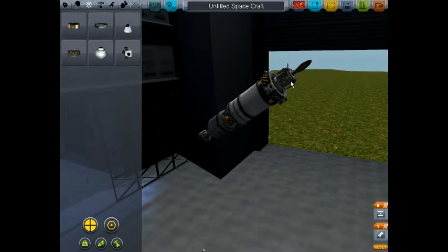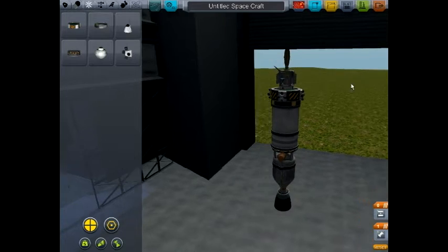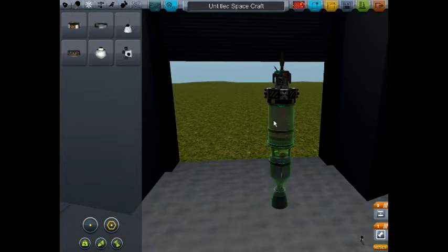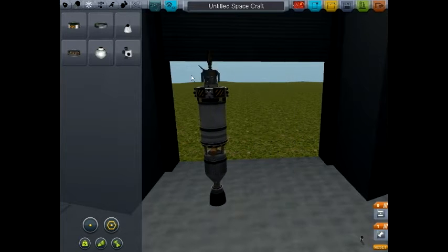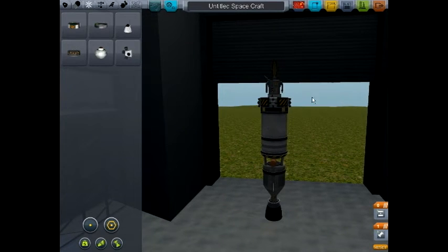And it's far easier to push an object on the ends, if it's long, than just to push it in the center. In the center, it would just kind of move like this. We want the pitch. We want it to change its angle, dive, climb. So I'm putting them on the end so they can help with that. Can't put them on the rocket, so I can't put them down here. The only other option I would have is in the middle. And they work, but it's a very bad place. It's very inefficient to put them in the middle of your object.